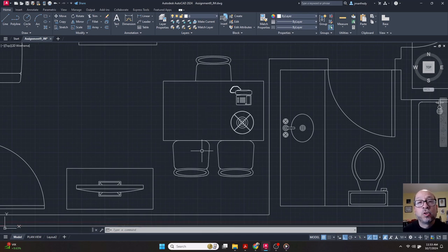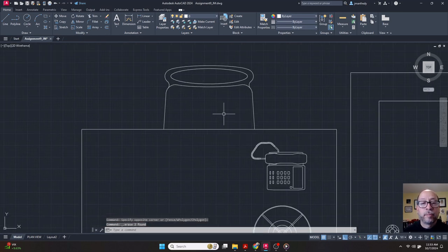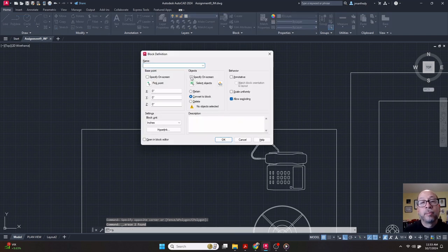But in AutoCAD, what you want to avoid is doing the same work twice. I've already have that chair located here. It's already been trimmed. I can use the exact same chair for these two here. So why not make a new block? So let's erase these for a second. Let's grab this chair here and I'll type B for block and I'll give it a name.